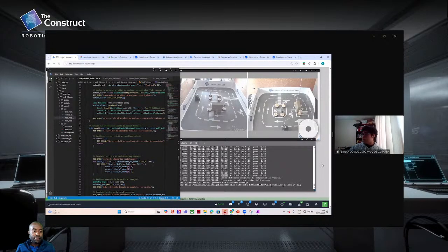And finally, we stop the recording to complete the trajectory. The main components are the service, the scan topic to provide the laser data, the cmd_vel topic to publish the velocity commands, and the record odometry action to record all the odometry points.